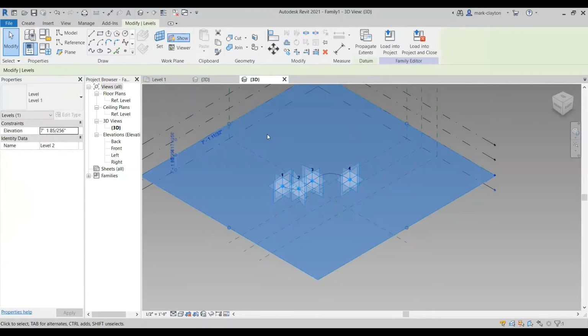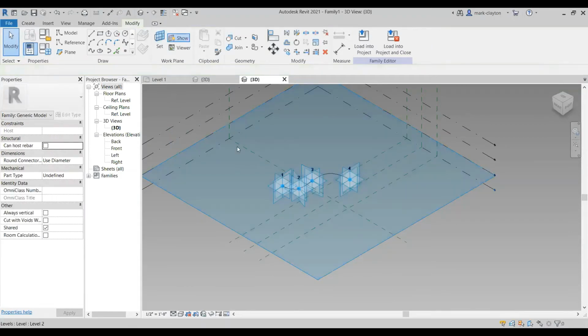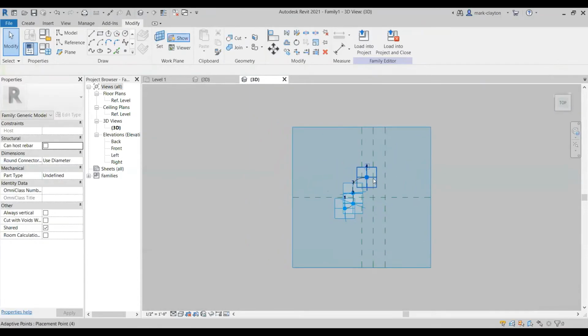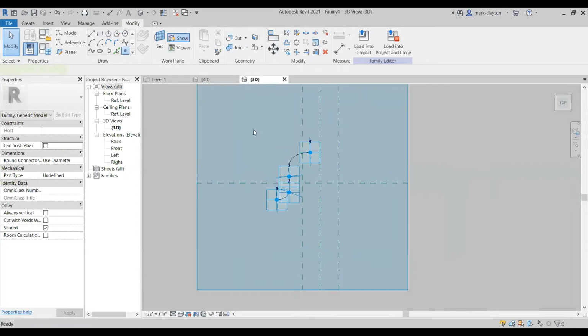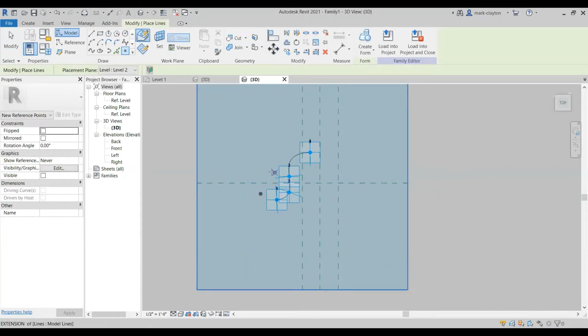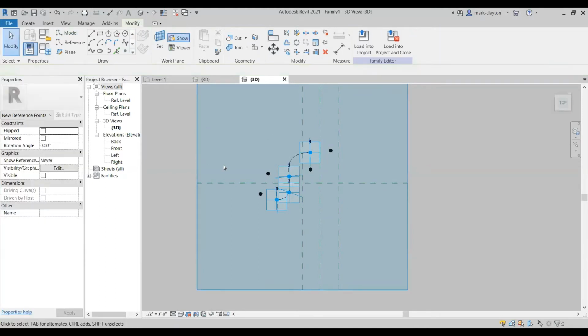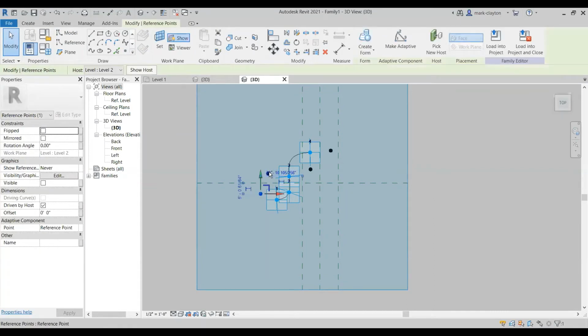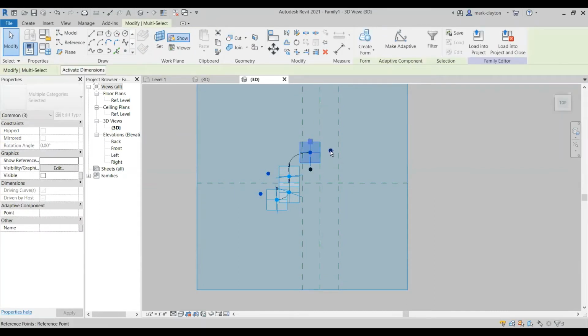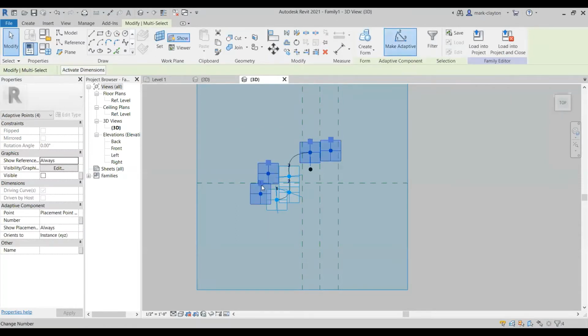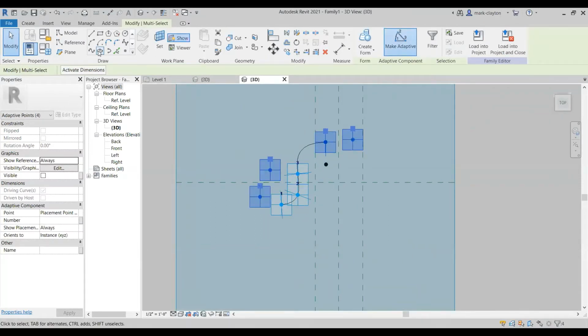If I go to this level, and I'm drawing on that level, I'm gonna spin around to the top view. Well, doesn't really matter, because we're drawing these crazy adaptive points. I'll control click to click those 4 and make them adaptive. These will be 4 through 8. And I'll create a spline through them.